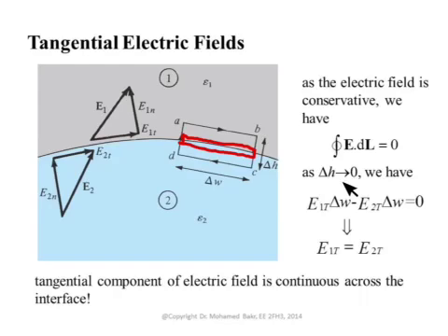Delta W cancels with delta W and gives us the result that all electrical engineers who work in electromagnetics know: when you move from one dielectric to another, the tangential component of the electric field is continuous. In other words, if the value of this tangential component was 5 volts per meter just before the boundary, it will still be 5 volts per meter just after we cross the boundary.